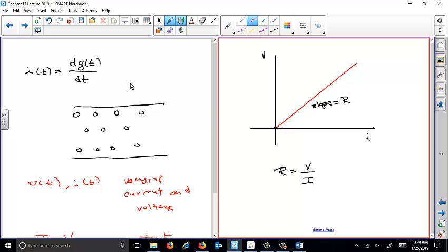Now, we've used resistors a lot, and we've used them with constant voltage, hence constant current. And it turns out that resistors have a linear proportional relationship between those two properties: the voltage, which is the electrical potential, and the current, which is the flow of electrons. So when we're running our little voltage divider, we're pushing current through both resistors, and the amount of voltage across each resistor depends upon the resistance. So for a given voltage, the higher the resistance, the lower the current. That's why we put the resistor into the other part of the circuit, the LED part of the circuit.